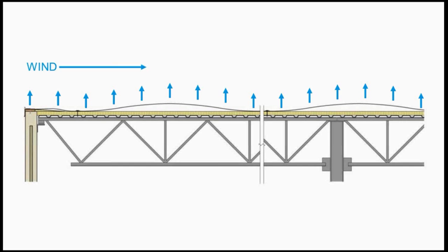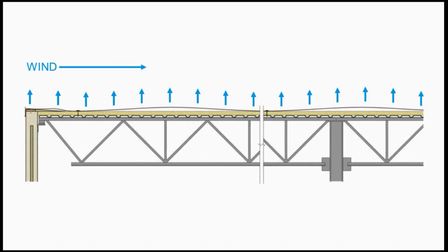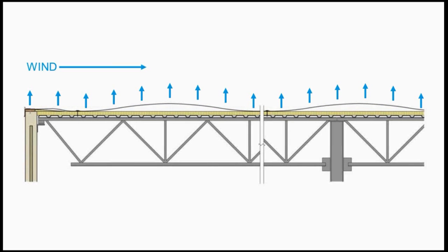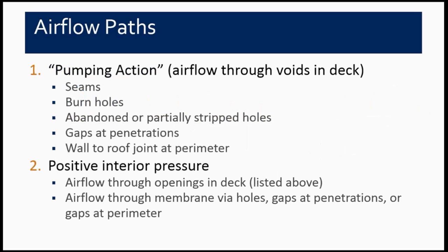This is a huge membrane. There isn't a lot of penetrations in it, and there isn't a lot of flow of air. But this is a big part of the area of the roof. You see this inflating during high winds, and it's because of a few things, not least of which is that the membrane is only attached at 12 feet on center.